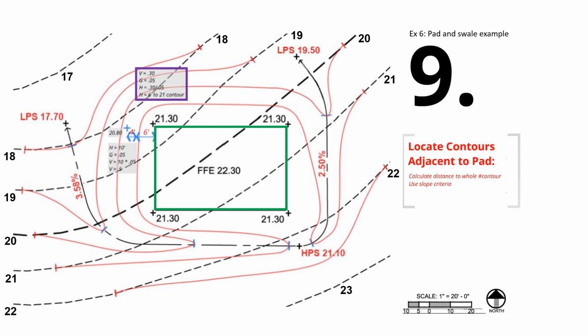What about the remaining 4 feet? In order to maintain 5% for that 4 feet, we need to have at least one additional spot at this exact location, 10 feet away from the building pad. Otherwise, the contractors won't be able to know that we have a flatter slope closer to the building, right?